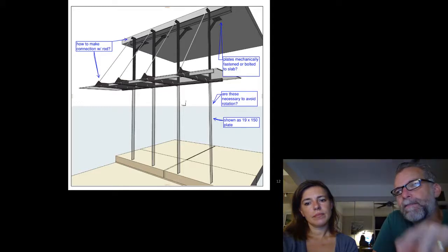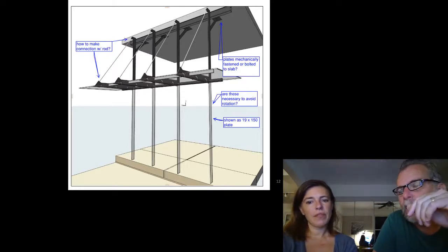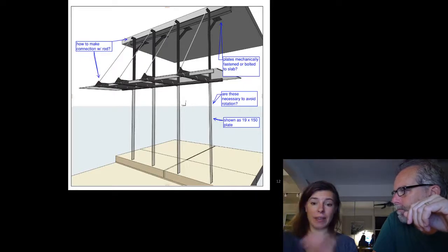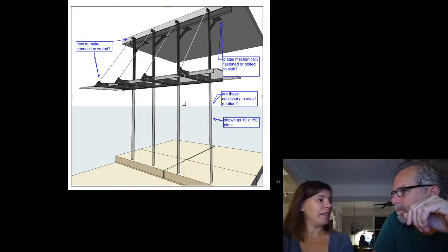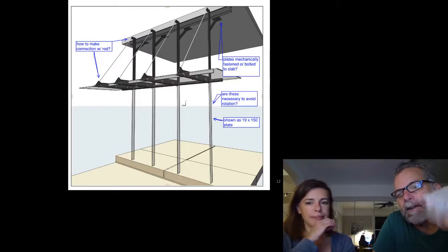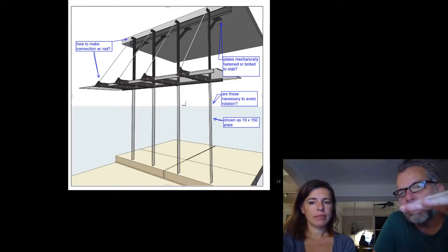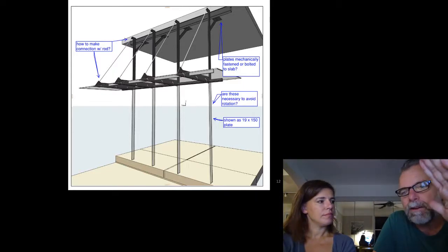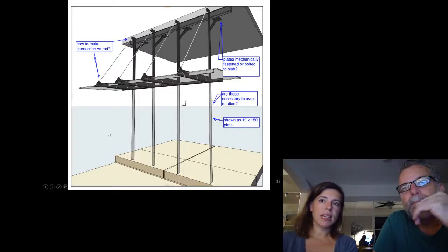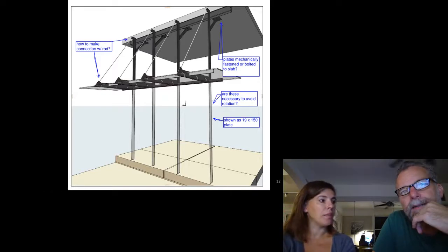One problem with the tension rod is if they do go slack, they vibrate, and they may even visibly go slack. Yeah, they can look like they've bent a little bit. It's like kind of pushing on an elastic band. You'll start to see that deformation. If it's too much, it could actually damage it. The other problem with it is that under uplift, we have dramatically less stiffness than under downward load. So as the canopy is vibrating, it vibrates from stiff to unstiff, and so it can actually thunk as the rod straightens. And if this is connected to structure in the building, that can really cause disturbances inside the building. It can be really noticeable.